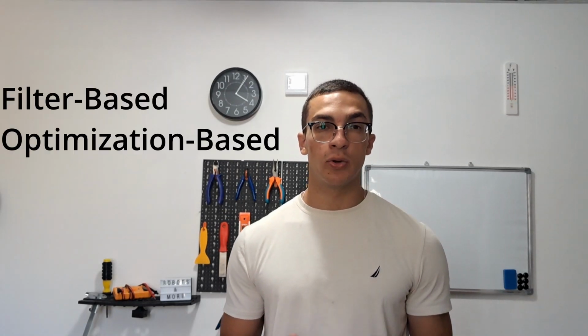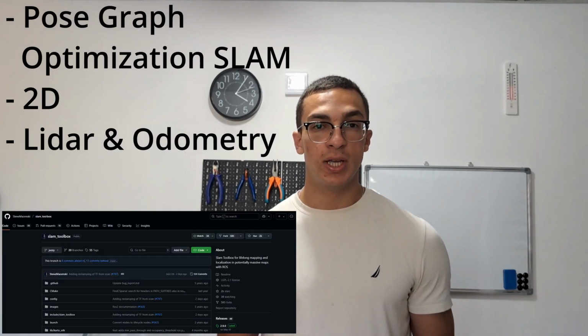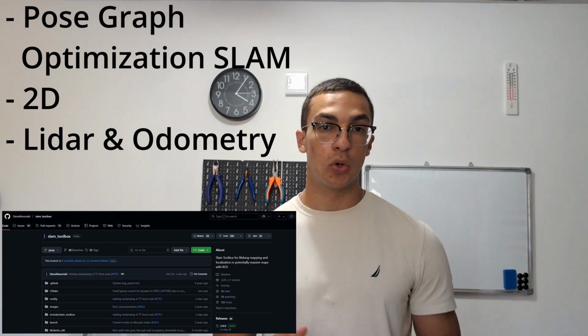There are many algorithms that we can use to achieve SLAM, with the two most popular categories being the filter-based and optimization-based ones. For my project, I use the SLAM Toolbox package that implements a pose-graph optimization technique for 2D LiDAR SLAM. For this package to work, we need an estimation of the robot's position based on odometry. This is handled by the ROS2 Control Package as I mentioned earlier. We also need LiDAR data. There are many types of LiDAR sensors. The one I used is a 2D LiDAR by Slamtec that provides a 360-degree representation of the environment around my robot. SLAM Toolbox uses both LiDAR data and wheel odometry to estimate the robot's position as it moves. It aligns each new laser scan with the existing map using scan matching.